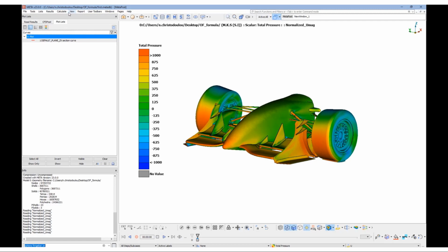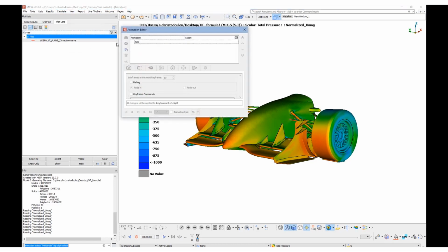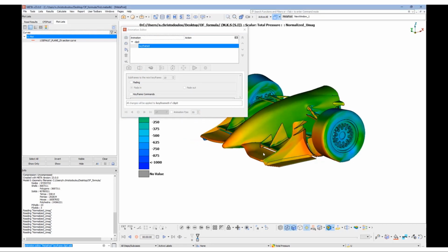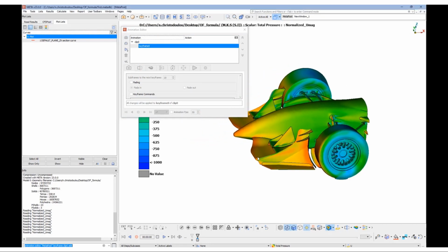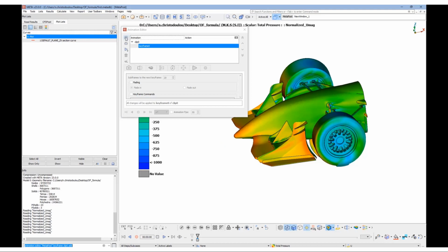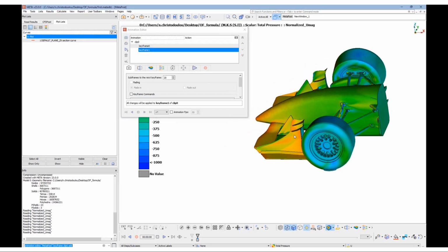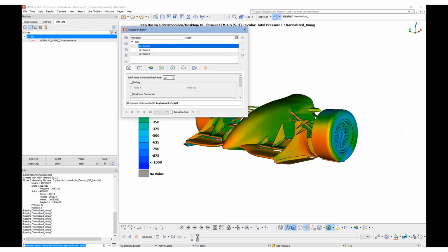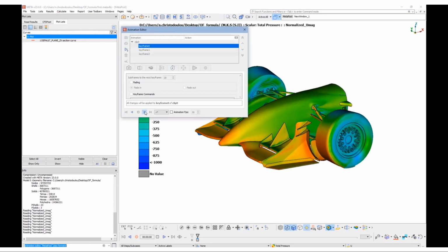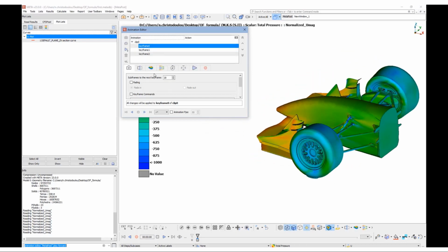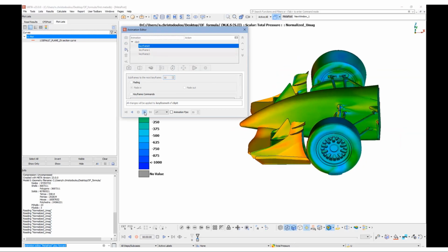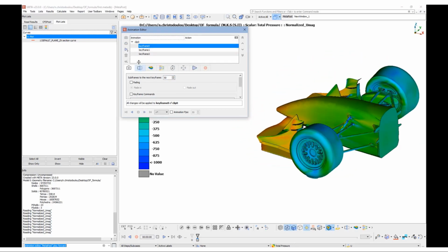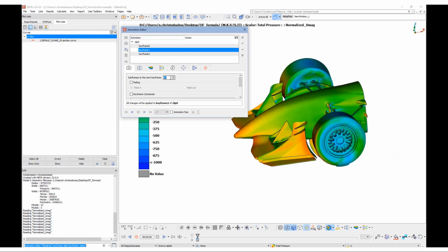Moving on, we can have a look at a handy tool that can help us create a cool animation. The animation editor takes snapshots of the model and links them in a smooth animation. Here, streamlines, cut planes, and ISO functions can be included. Let's try this small animation of 3 keyframes and see how it looks. By changing the subframes into a bigger number, we will make the animation smoother. Let's do that for all keyframes.